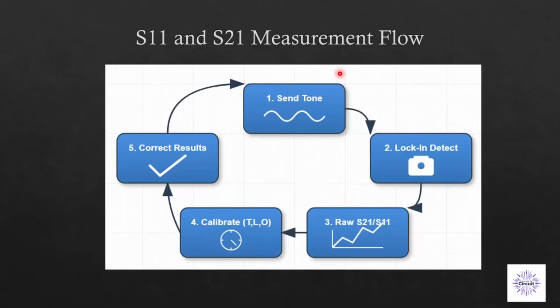In the previous video, we talked about how we can make a frequency analyzer which measures S21 using the lock-in amplifier we made. Basically, we send a tone, which can be at different frequencies, using our ADALM-Pluto. Then that transmitted signal is connected to the input of the device whose transfer function we are interested in. Then its output is connected to our ADALM-Pluto receiver. Based on that, we can measure how much is the received amplitude and measure S21.